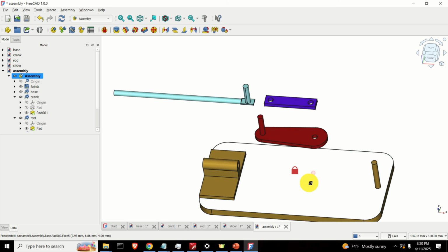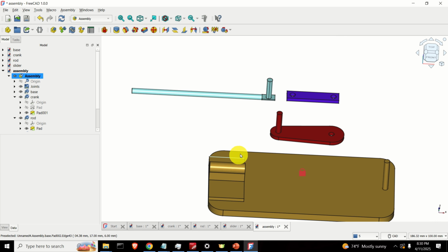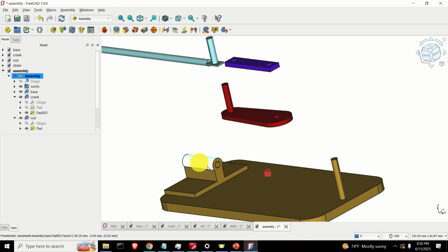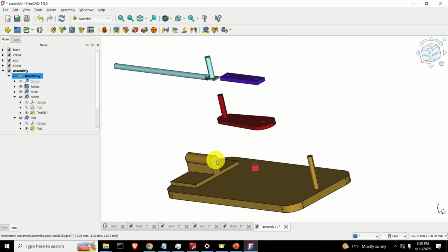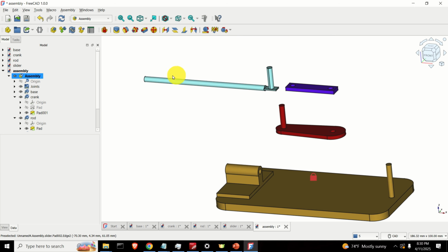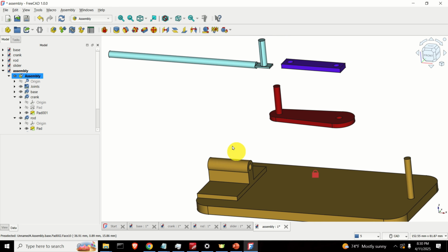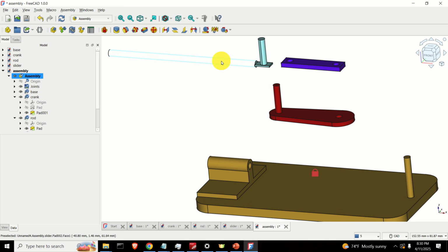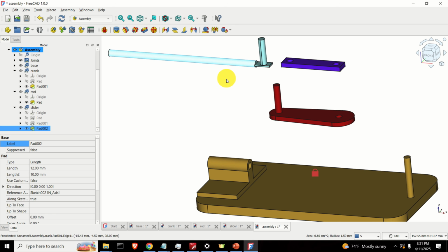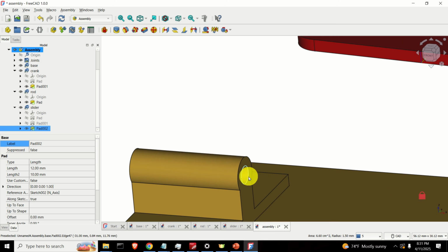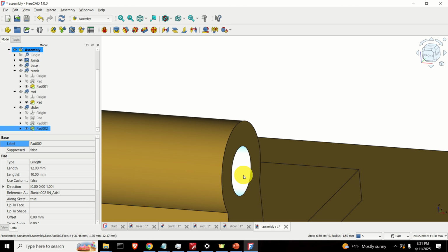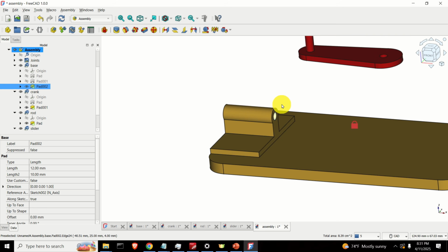To create our joints, we first need to do the following. We need to create a linear joint or a slider joint between this slider and this support. Not a big deal. How to do that? Well, click here, then press and hold Control, and then click over here on this inner surface of this hollow cylinder. And now you select it.